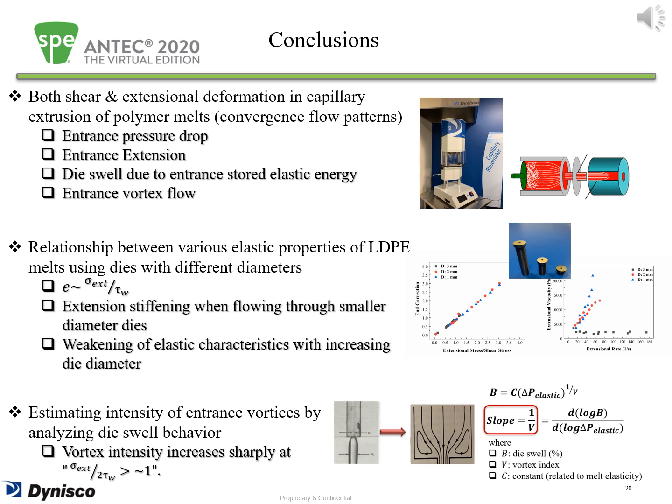Moreover, by analyzing the die swell behavior of the extrudates, we proposed a numerical approach to quantify the intensity of the corner vortices at the entrance flow. Finally, we concluded that vortex flow intensity increases sharply once the extensional stress to shear stress ratio is higher than about 2.